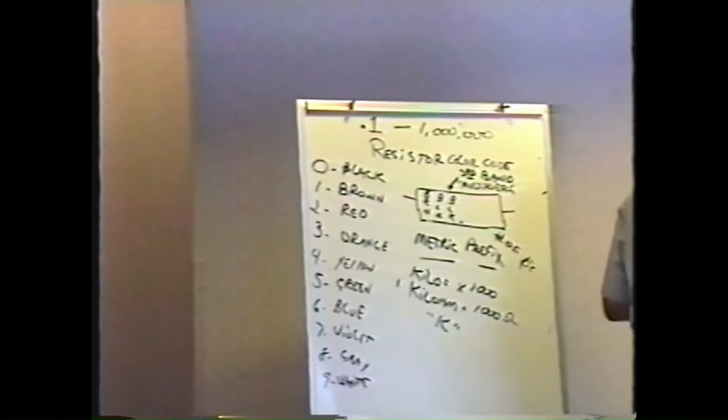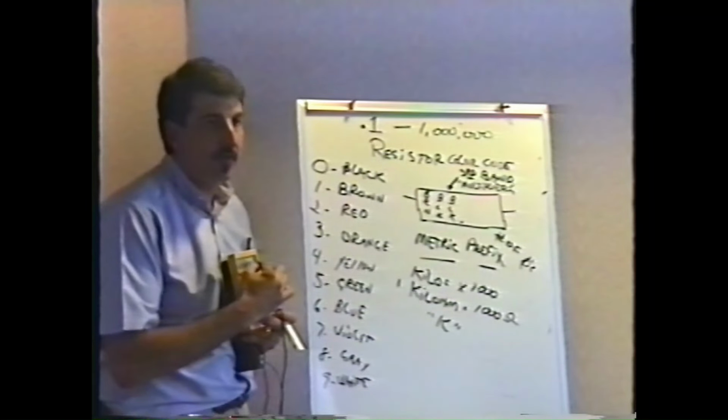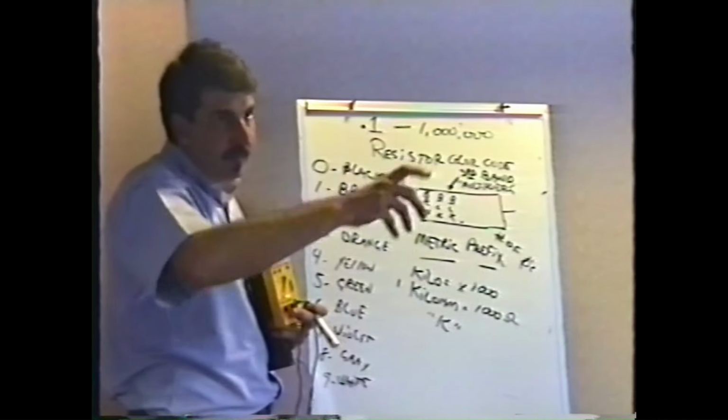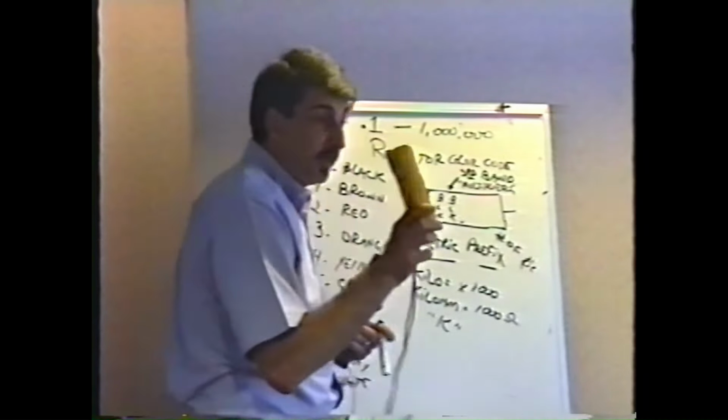You'll see a little K in the upper corner, usually, of the meter. Maybe it's real big. It depends on the meter you get. That tells you how many ohms it is. But my little K is a teeny weeny tiny little letter in the corner of this meter. If you're not careful, you may think you're reading 10 ohms, but it's really 10K, where you won't have that problem if you have the other type of meter. But some people prefer auto-ranging meters. It really doesn't make that much difference.